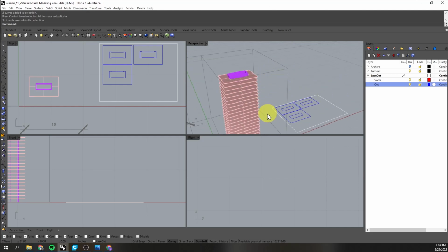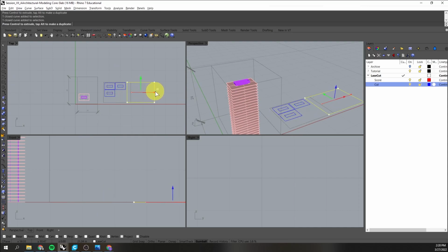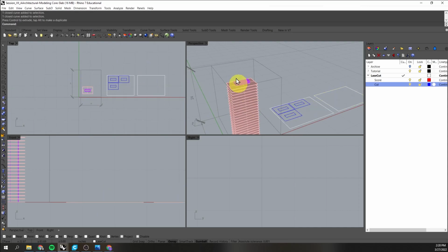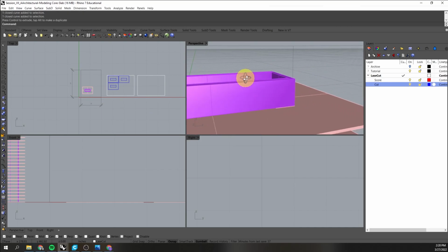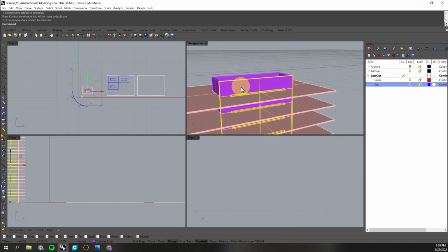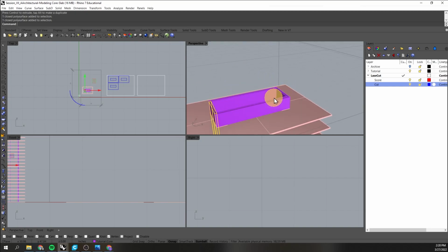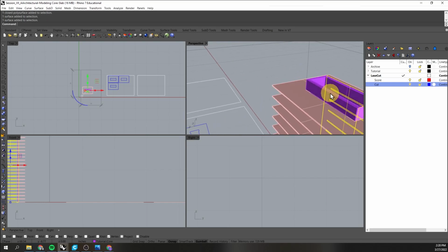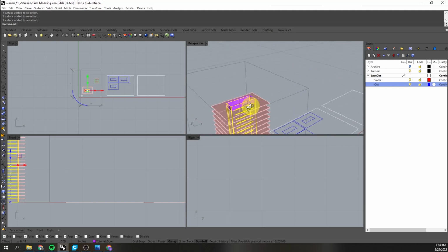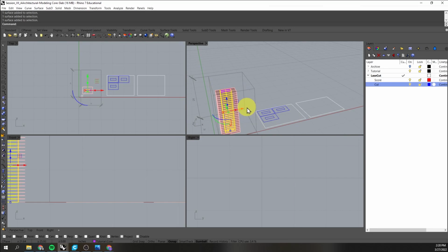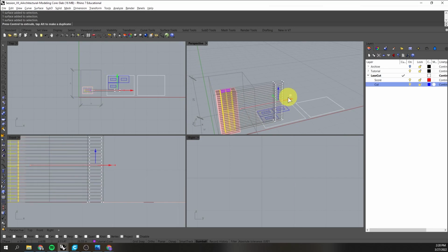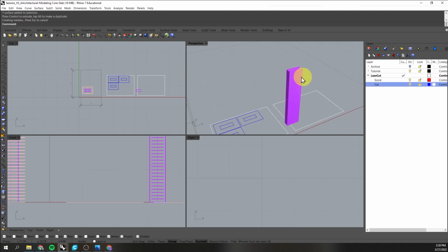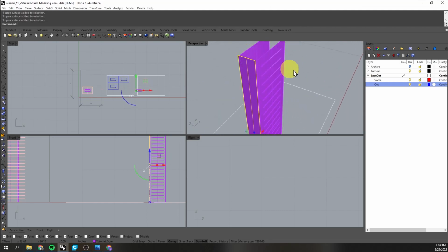And now, how do we get our slab ready for cut? Let's make a copy here. We have four parts plus the two interior. We have six parts, so three unique parts that repeat. So we're going to select the front there, we're going to select the side, and we're going to select one of the interiors. And while pressing the Alt key, I'm going to make a copy of those and just bring them over here. So notice I only have the surfaces now.